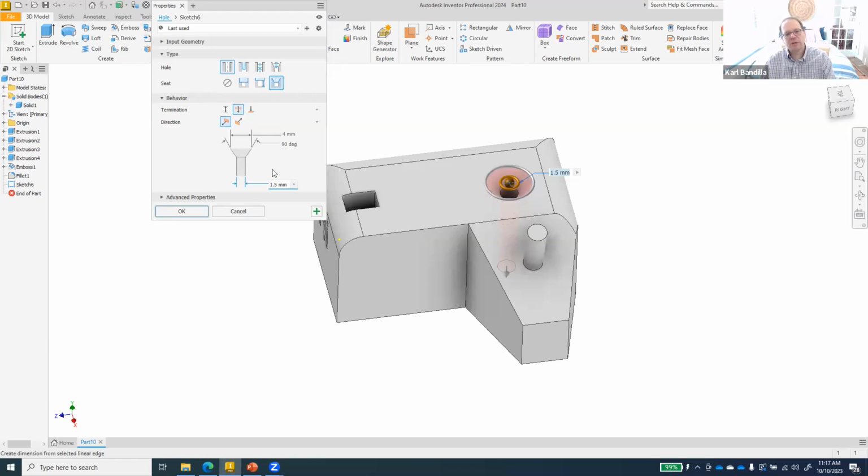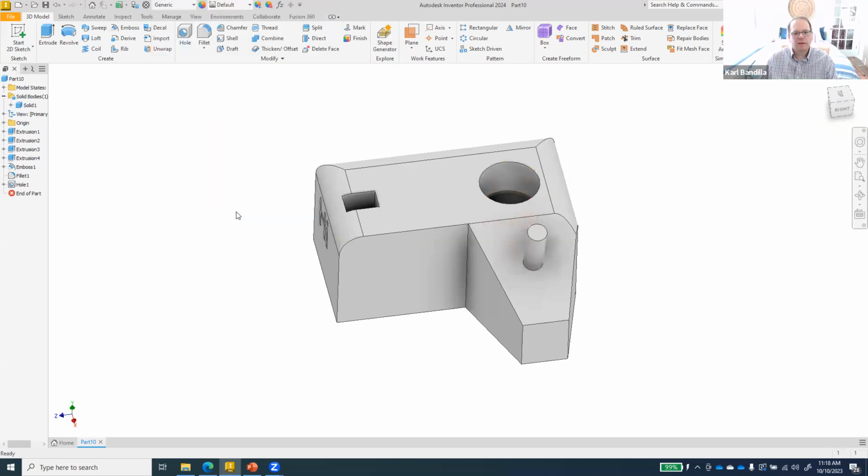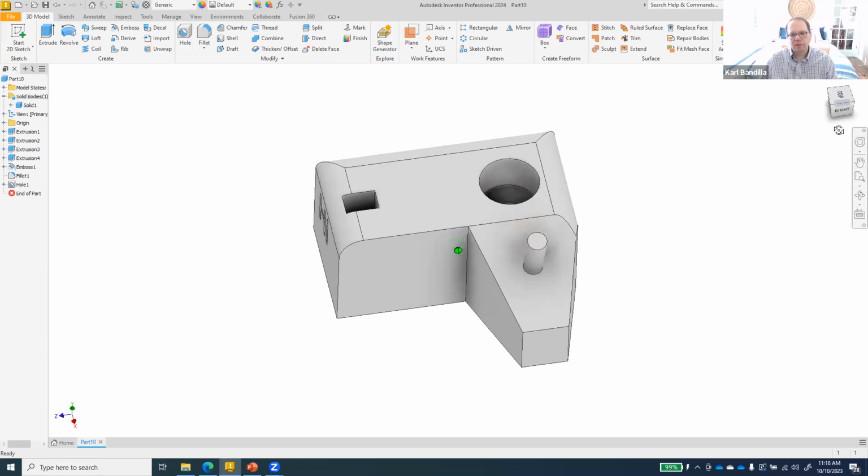And for each of those, again, we can change what size we want to have, right? Go back to my countersink here. Maybe I want it to go in a little farther. Maybe we'll say 3.5 millimeters, and maybe I want this to be bigger, and I'll choose 5 millimeters, right? And so then if I hit OK, then I have my hole built in there.